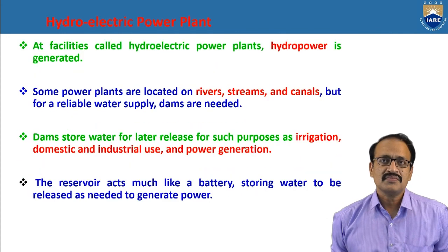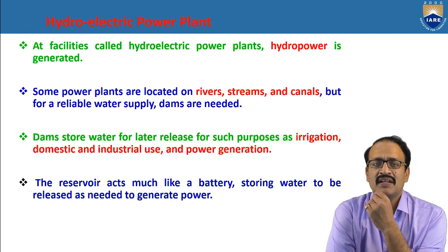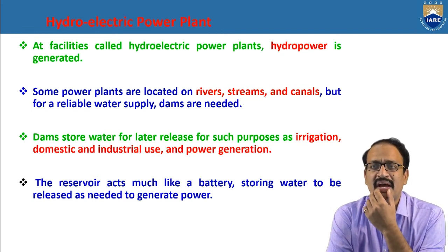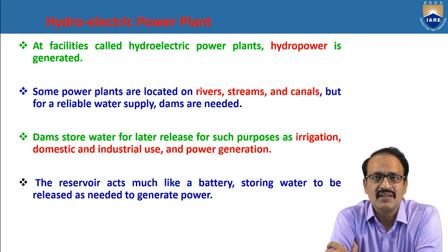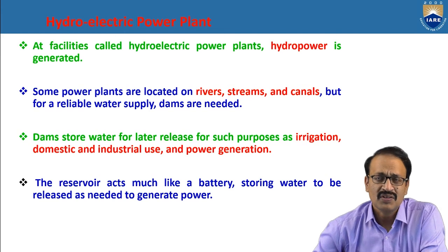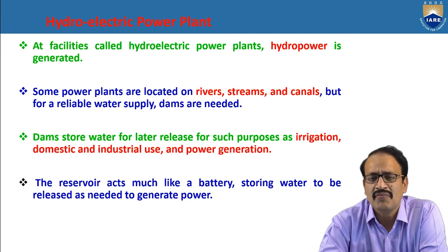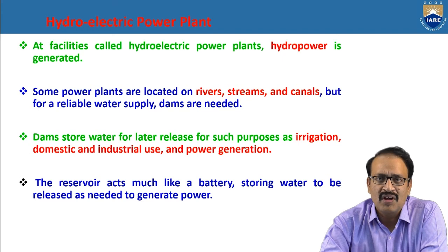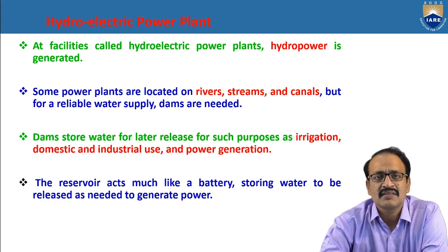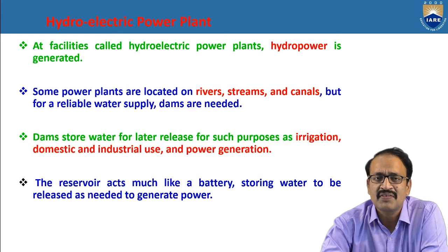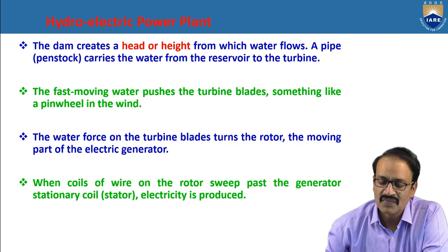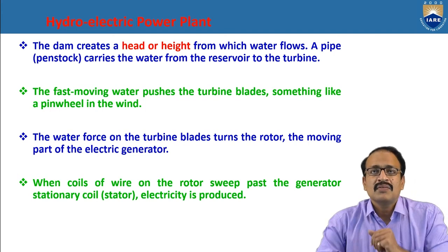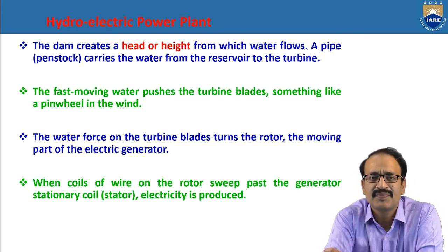As I told earlier, this dam will act as the battery. We can store the water, and we can release that water whenever it is needed. Even though we can generate a small amount of power with the help of small rivers, streams, and canals, the reliable supply will be with the help of the dams. The dam creates the head.